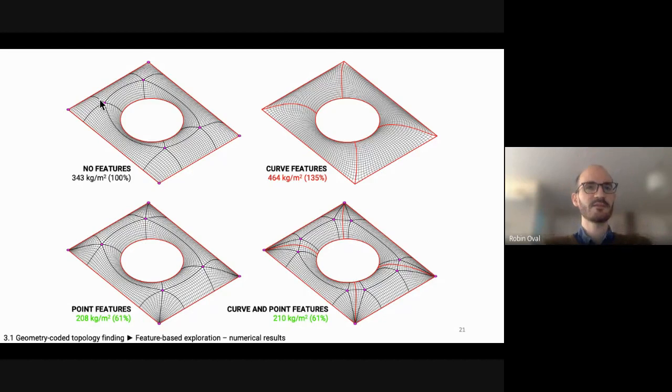For this example, I get the coarse mesh and I do the densification, so in that case there's no front panning. I'm mapping it on the target shape, and it's through relaxation that you get the singularities that slide on the shape. If you were to have this part much denser, with relaxation, this would move inward. So there's topology, geometry, and this density in between, that might require some tuning or potentially some optimization. That's at least a nicely structured space.